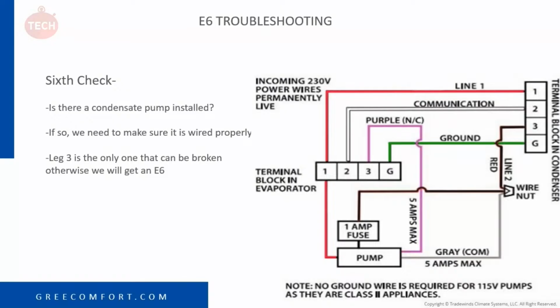Obviously, we can't break leg number 2 at all. But leg number 1, the unit will beep when it shuts down if you break that leg. So we don't want the unit beeping. That would upset some homeowners.